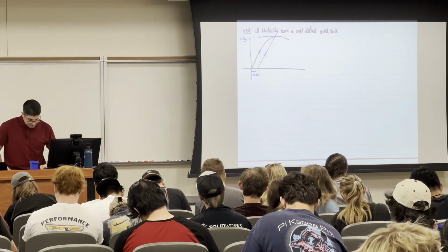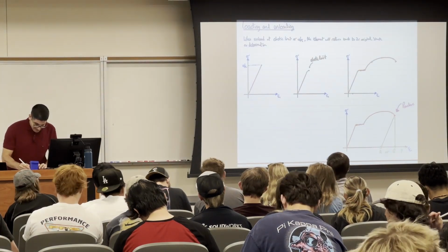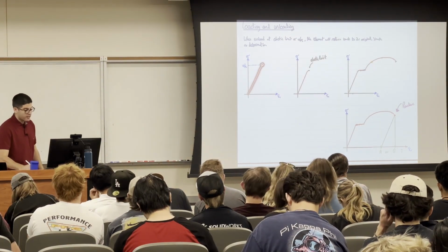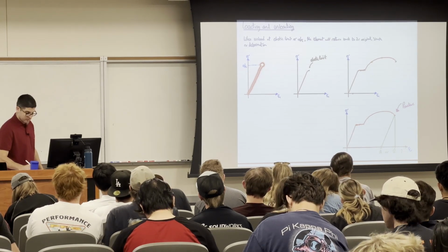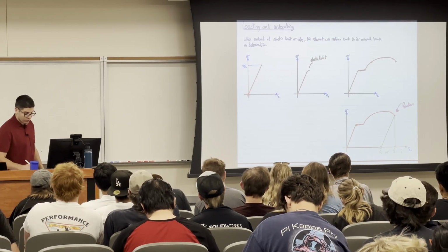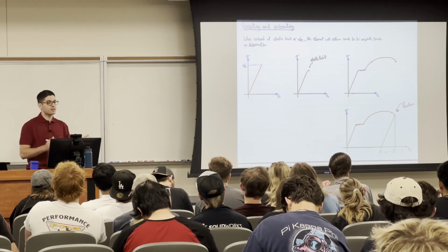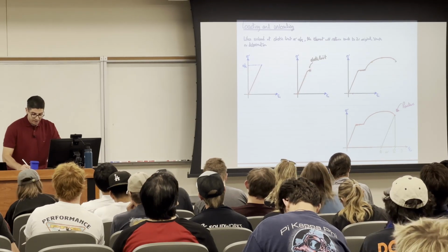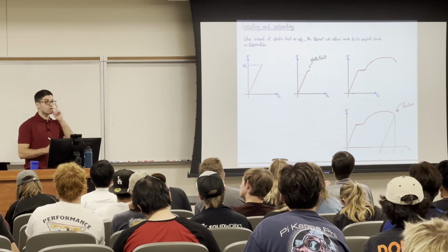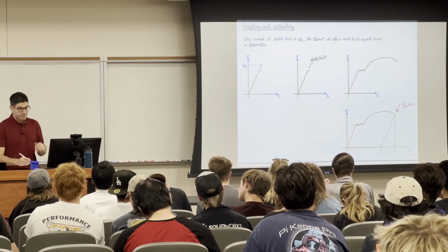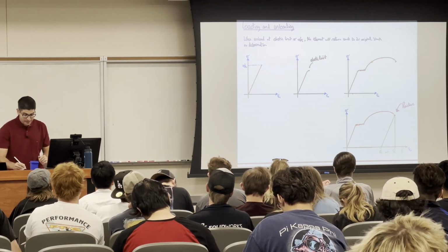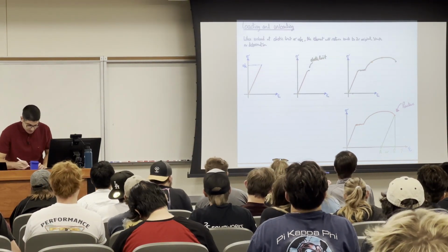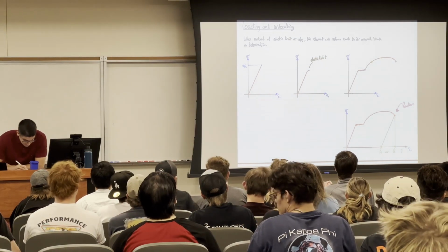Okay? I have a minute, so last thing. But you all are going to help me with that. You all know when I apply a load up to the proportional limit and unload, it's going to go back to its original position without any permanent strain. Same thing with the elastic limit. If I apply a load until the elastic limit, it's going to go back to zero with no permanent strain. But beyond the yield, any point here...